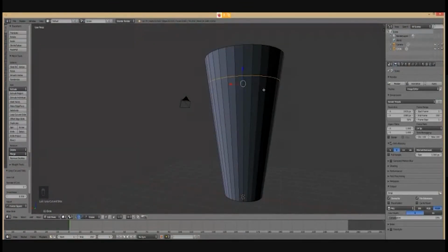So let's assume I want to keep it somewhere here. Okay, cool. Now I want another loop cut like this somewhere here. So again, I'll just select any random line, press Control plus R, and then I get another purple line. Left click once, and then I can move this as well. Let me just keep it somewhere here. Okay. So now I've got these two lines that run like this. If I go back to choosing faces, you will now notice that instead of one strip, I have the ability to choose. Each part is now divided into three faces, right? And this is exactly what I wanted.